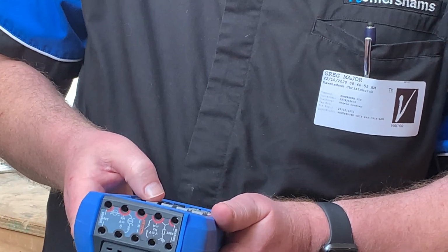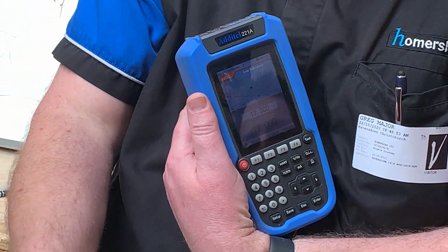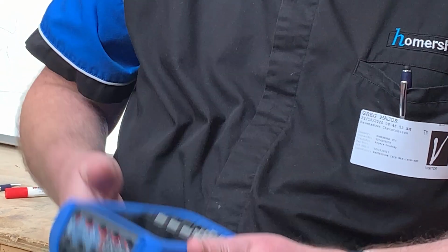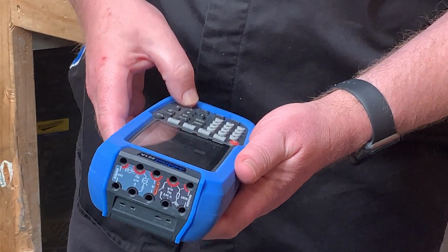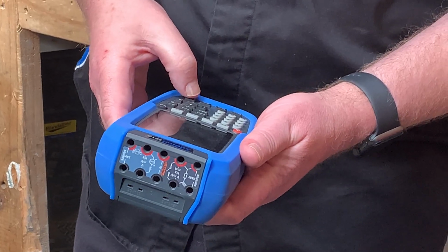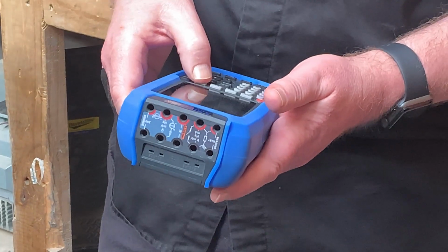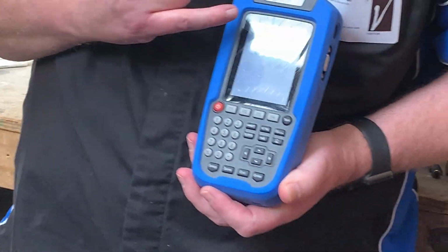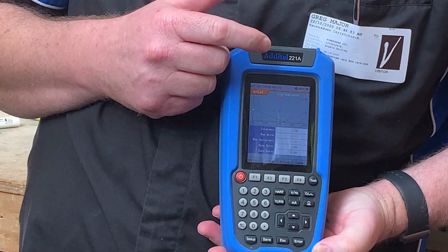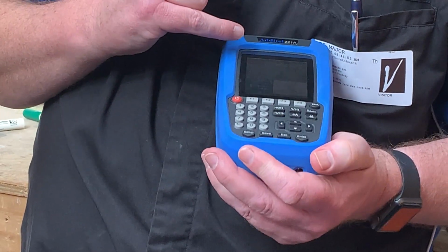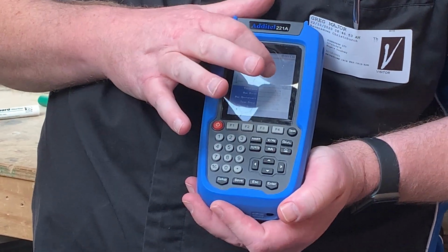We'll accept that, and then it will do the same on falling, because you want to allow for hysteresis. So we'll do the same again. We'll say it was fine, fine, fine, fine, and it will draw a graph. Accept. So in this case, there's your summary. On rising, it was really poor. On falling, it was really good. The acceptance criteria we said was 1%.